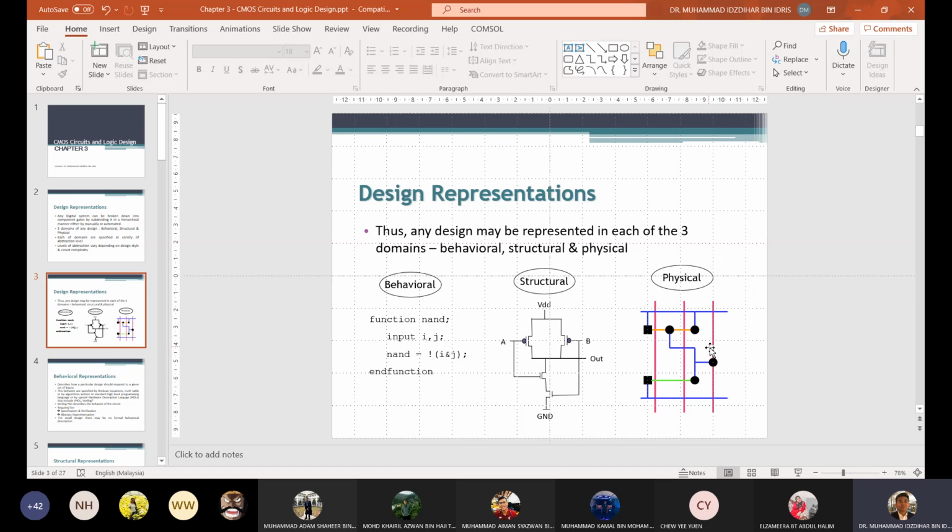So let's say if you want to design a transistor, you must know the minimum width, or the minimum line you can make. Otherwise, maybe you need less than 1 micron for a specific reason. But unfortunately, if you're using this technology, it's only up to 1 micron.